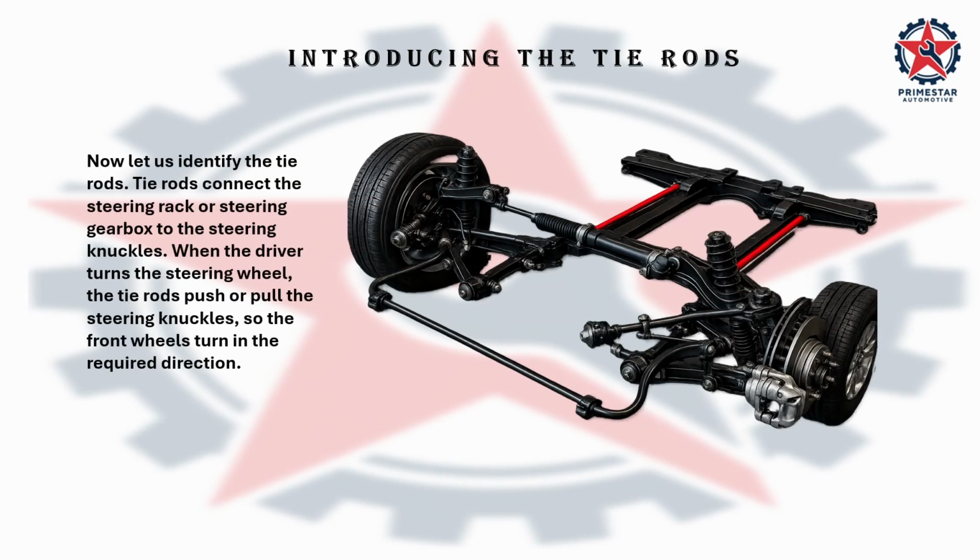Now let us identify the tie rods. Tie rods connect the steering rack or steering gearbox to the steering knuckles. When the driver turns the steering wheel, the tie rod pushes or pulls the steering knuckles, so the front wheels turn in the required direction.